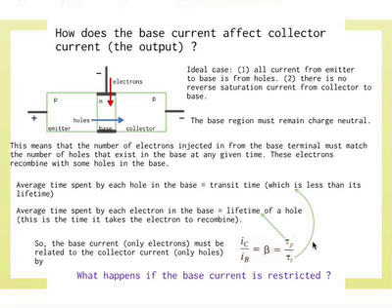So if I don't do anything to these, nothing happens to these currents, what happens? I start building up positive charges within this box. Right? I have all these holes coming in, and I have the same number of holes going out, let's say. Fewer electrons coming in, meaning the whole box is getting positively charged now. Right? Excess holes. Not enough electrons to do the recombination.